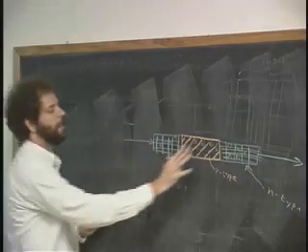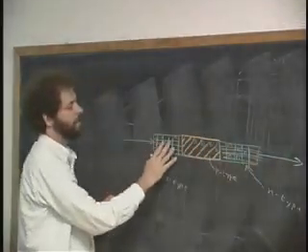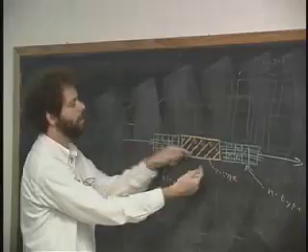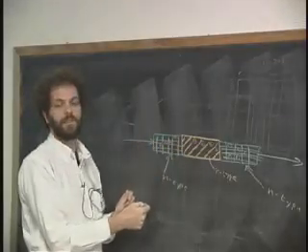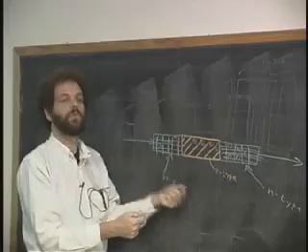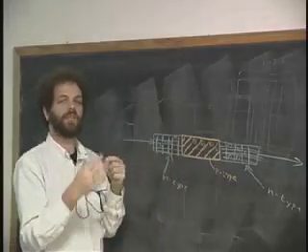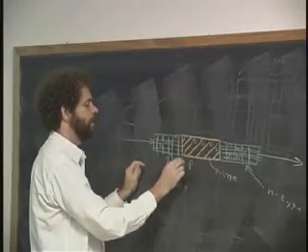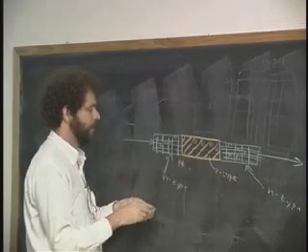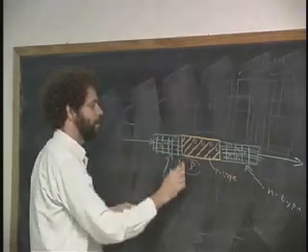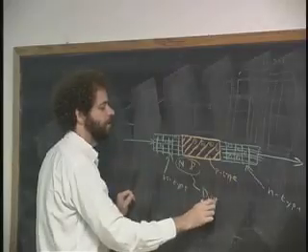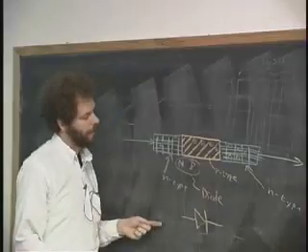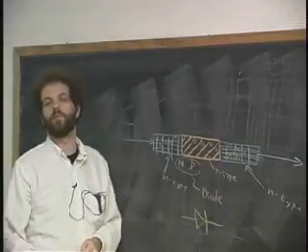In general, if we didn't have this thing on the right, if we just had some N-type over here and some P-type here, and they had a junction in the middle, and we tried to pass current one way through that junction, it would allow the current to go one way, but it would not allow it to go the other way. We don't have time here to explain exactly how, but what's called a PN junction, or an NP junction, here's N and here's P, is what forms what's called in electronics a diode, which is often drawn like this. In other words, a valve that only allows current to flow through one way.